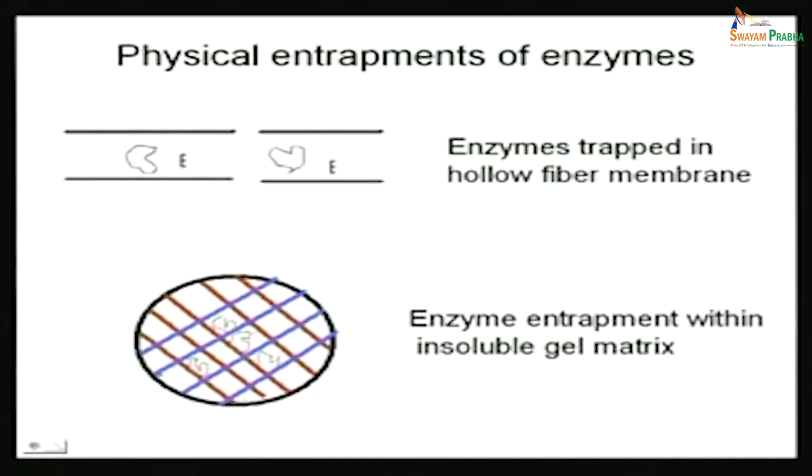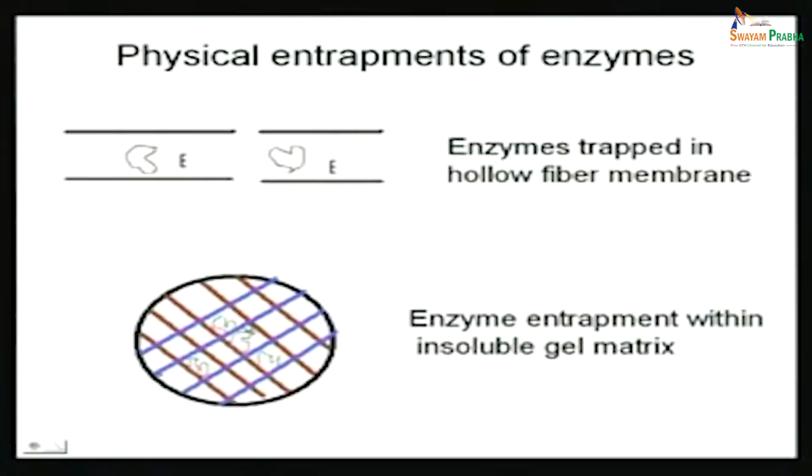So that's the difference. If you have intraphase mass transfer, where the immobilized enzyme is entrapped within the encapsulation, within the gel or the matrix, then there is no way for you to make it react with the substrate without the substrate actually diffusing into the enzyme, right? Intraphase is intra, within the phase. So mass transfer should happen within the phase. And when you have intraphase mass transfer, the reaction occurs simultaneously, right? So that's a major difference.